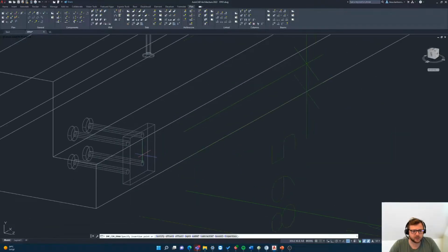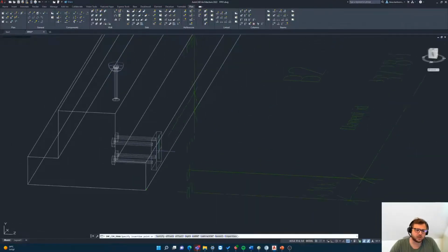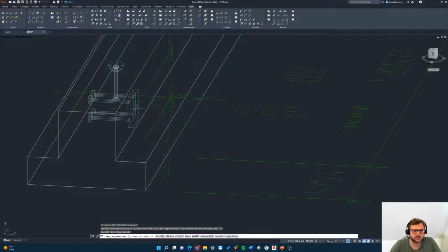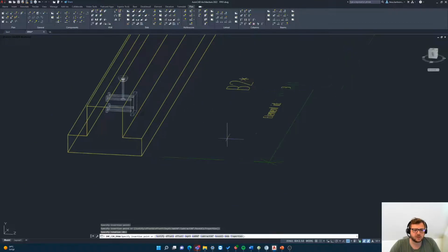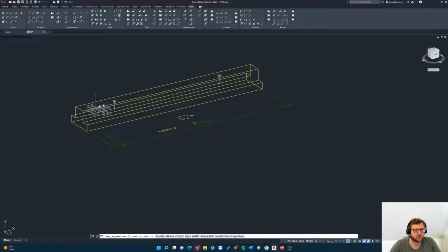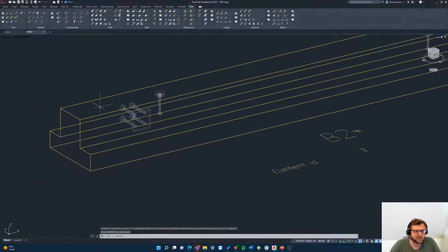And you can see here that now, even if I'm in the side or top or whatever, it's only going to put the custom material in this front face. But maybe I want to put it in this face. It's also the front. Then I can just use this move UCS and select a point where the new UCS is. And then I want to place it here. No rotation. And it works really nice. And this works, of course, for other sides as well. So if I put top, then I can select this one or this one, for instance.